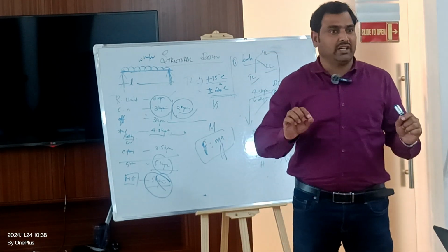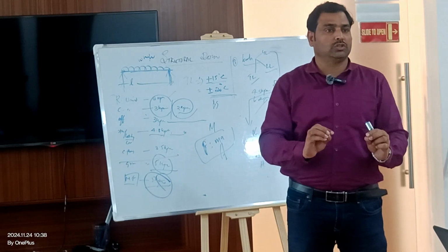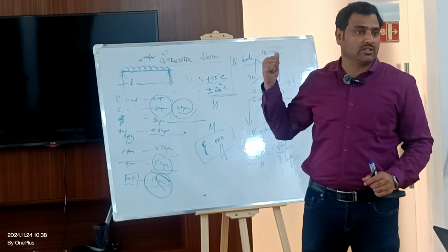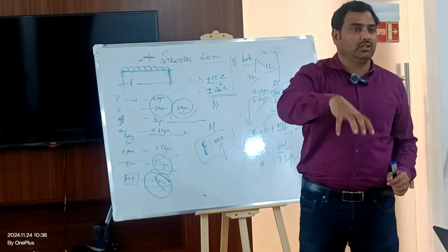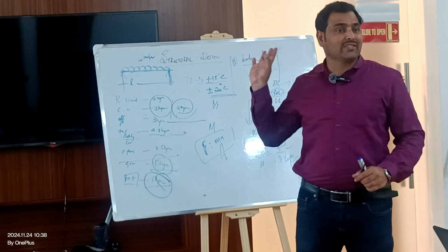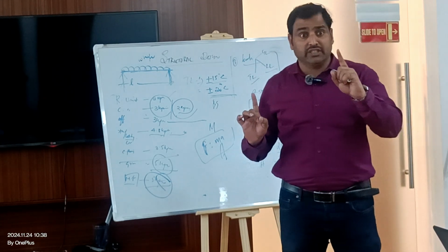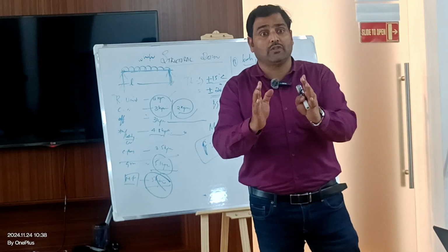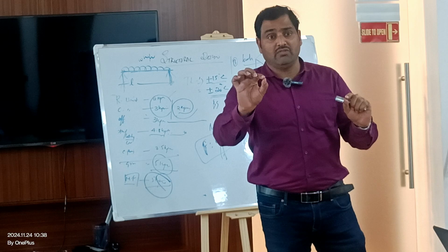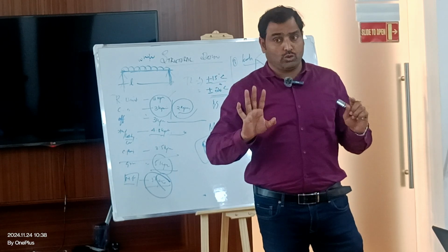The code doesn't have any specific guidance on what you need to consider for walls and slabs. The minimum temperature the code says is 15 to 20. But this 15, 20 is set by authorities, based on the localized conditions where exactly you are going to design. This is there in the DBC code. The Dubai Building Code 2021 did not mention the particular elements, they have given it very vaguely. For substructure 15, for superstructure 20, for steel structure 25. That's all. So don't consider the walls.